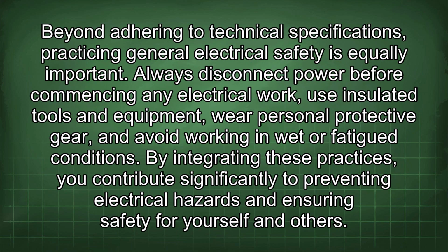Beyond adhering to technical specifications, practicing general electrical safety is equally important. Always disconnect power before commencing any electrical work, use insulated tools and equipment, wear personal protective gear, and avoid working in wet or fatigued conditions. By integrating these practices, you contribute significantly to preventing electrical hazards and ensuring safety for yourself and others.